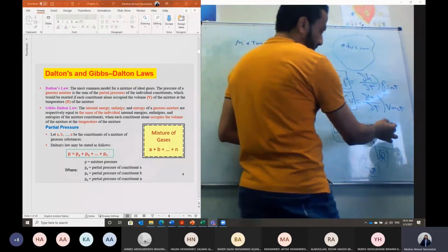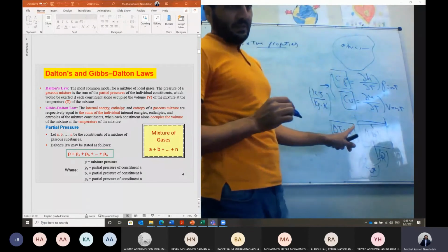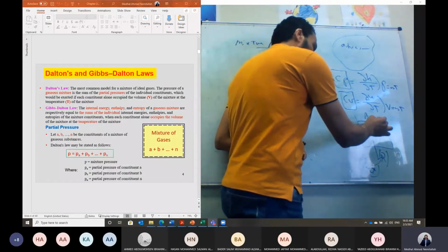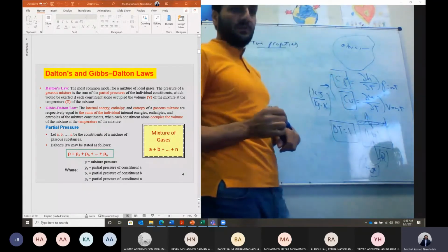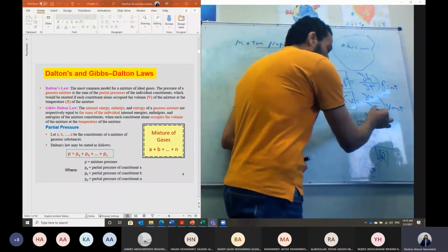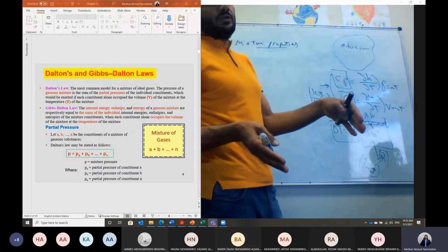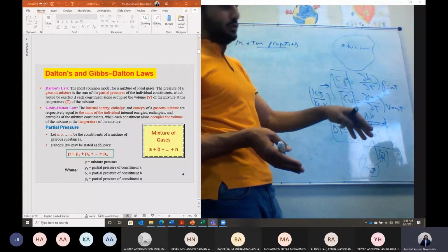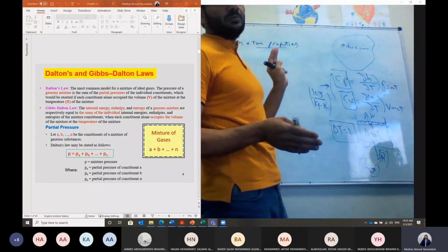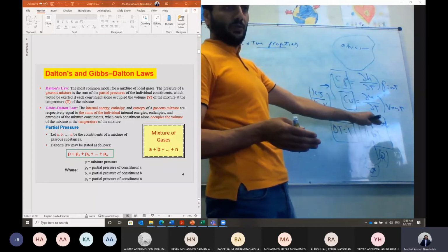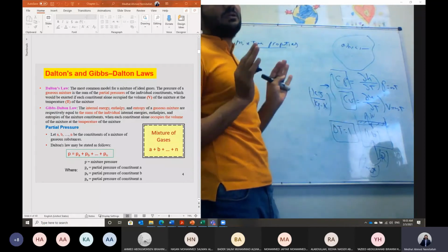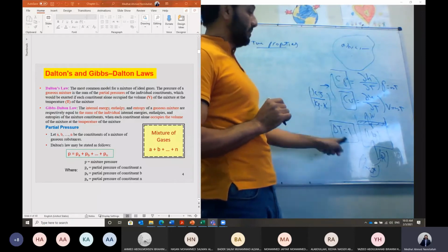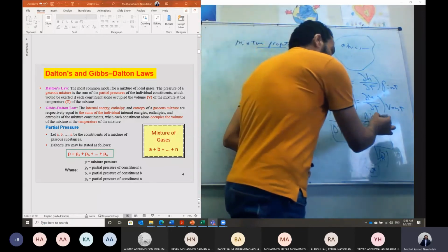So the only way to have heat addition under constant pressure is through the movement of one of the boundaries. If this is a piston cylinder device, this boundary should be moving, because the gas will try to expand. If you want to keep the pressure constant, you should allow for this expansion and leave the piston moving. If this piston is closed, not moving, then the pressure will be raised. The gas will try to expand, no movement, so the pressure will rise. So in order to add heat at constant pressure, the boundary will be moving.